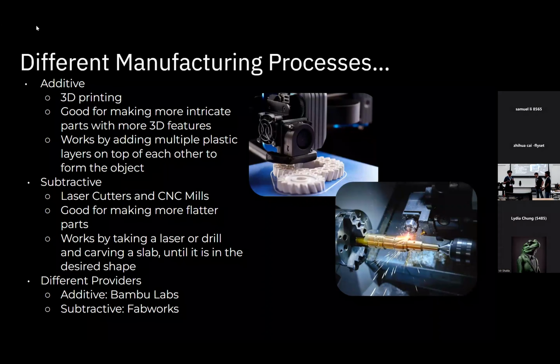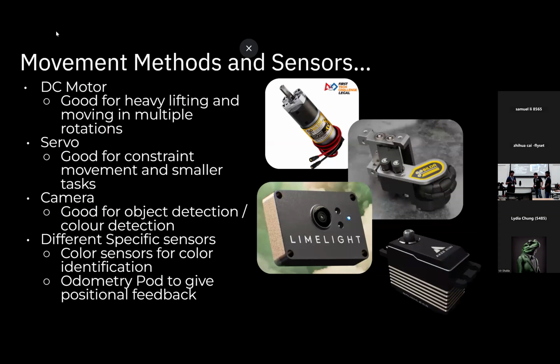Now, let's talk about the basic hardware that you need once you've got your chassis fitted. First, you will use some motors and sensors, and this helps with the mobility of the robot. Servos are much better for certain uses, such as arms and certain moving claws, because they're precise and good for lightweight pieces. Motors are used for chassis and slides, which makes them much better for heavyweight loads and far more efficient.